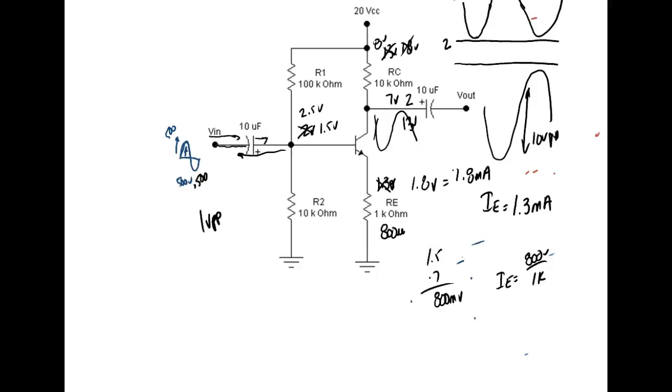Just take this resistor and divide it by that resistor, 10K divided by, and that gave me a what? Gain of 10. And I told you we had a gain of what? 10. 10 volts peak to peak out, 1 volt peak to peak in. Are we going to get power gain? Odds are we will.